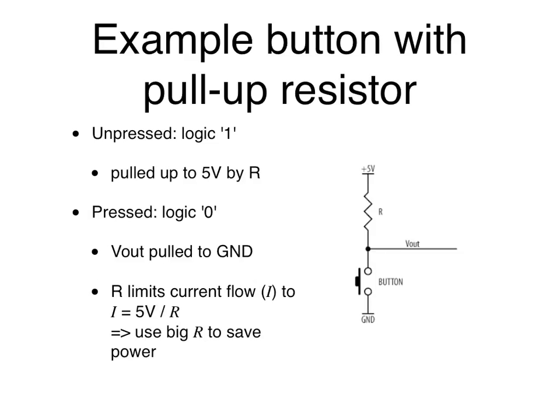You have to prevent somebody from attaching V out to ground, because if you don't have the R, you have a short circuit, right? So the R there is to limit your current. And when it's high and you're just measuring the voltage, there's not a lot of current flowing through, so that's okay.